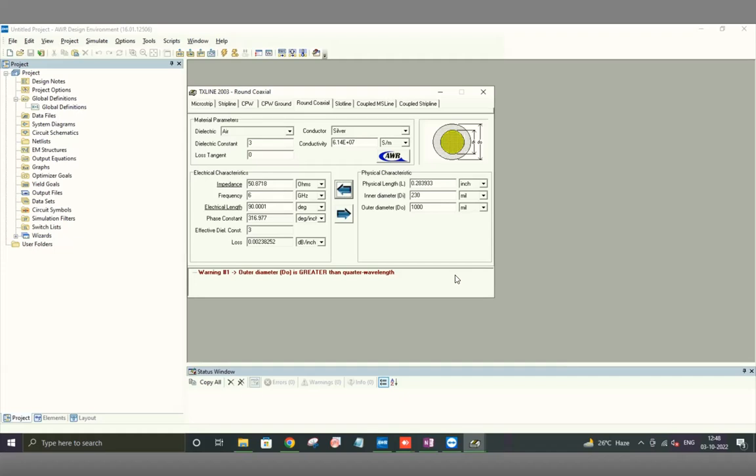And you want in the coax all the action to be happening along this direction, not in this direction. So things should not be varying. There should not be a phase difference as you go along this dimension. But that basically means that there are other kinds of modes of propagation which will come in. So this general idea of what these dimensions should be applies to all other types of transmission lines as well. Everything doesn't just scale continuously.